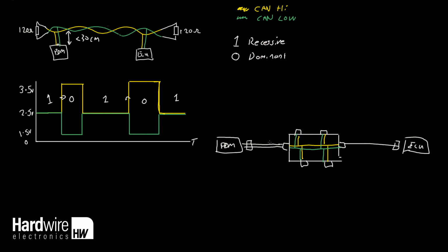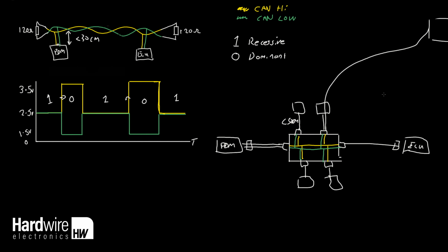This is still a CAN bus at this point. And then all you have to make sure is that the stubs coming off here are less than 30 centimeters. Like this. And as long as these distances here to the main bus are less than 30 centimeters, you'll be absolutely fine. You won't get any issues. It's when you start increasing this out over here and it's going off to the back of the car and it's coming back again, this is when you start getting problems. So that's just a little tip when it comes to using these passive CAN bus hubs.